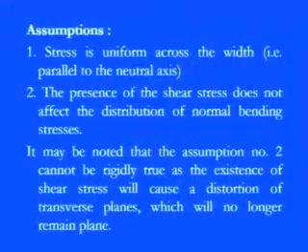And it may be noted that assumption number 2 cannot be rigidly true. Sometimes the existence of shear stresses will cause a distortion of the transverse plane, which will not be exactly the same plane. That means once we remove the load, it will not be exactly in the same plane before and after bending. So, sometimes this assumption 2 will not be valid for certain cases, but in general cases we can agree that these are valid.